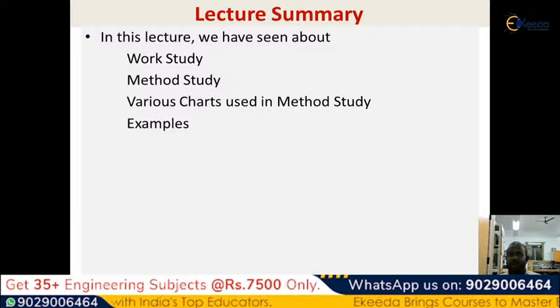Then various charts. There is the outline process chart, which indicates your broader perspective of the job. Then flow process charts we have seen. Then how you are going to use your two hands, that is two-handed right and left hand charts. Then you can have the man machine chart, meant for how you are going to utilize a particular man between two machines. I have given an example for that. Then travel charts, used to decide how you are going to modify the location of a particular machine according to the number of products traveling between the machines.